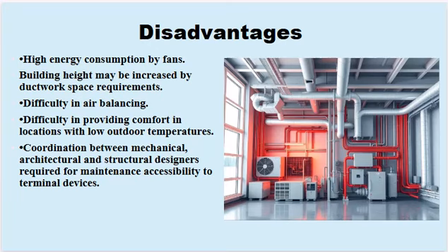Another issue is air balancing challenges. Achieving even airflow and maintaining consistent temperature control can be tricky, particularly in large spaces with multiple zones. We also have comfort issues in very cold climates. HVAC systems may struggle to maintain comfortable conditions when extremely cold air infiltrates the building.